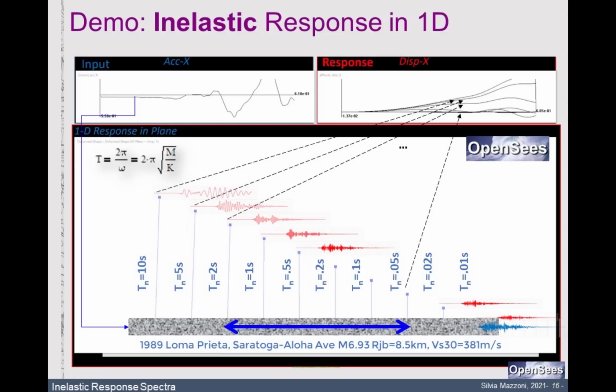I'm big on demonstration. So now what I have is, again, still in 1D, and these are structures that right now, the two models are overlaid, where you've got the elastic and the inelastic structure right on top of the other, okay? And so you don't really see the difference. But as soon as the amplitude goes up, and you see these are different periods and different strengths, you'll see that as now we go into the inelastic response, you start seeing yielding. And your overall response is different.